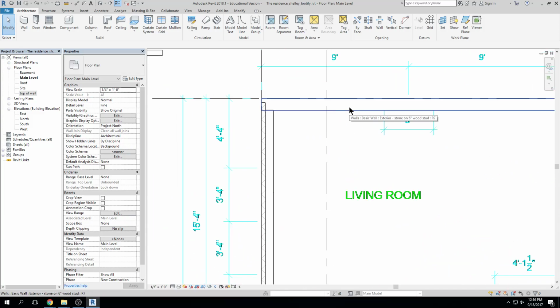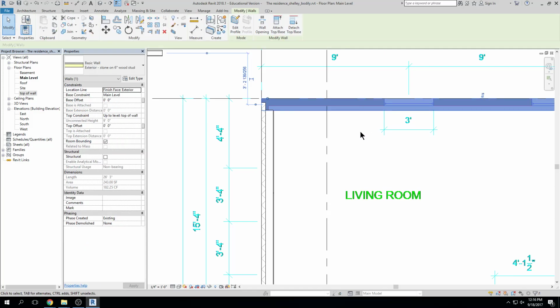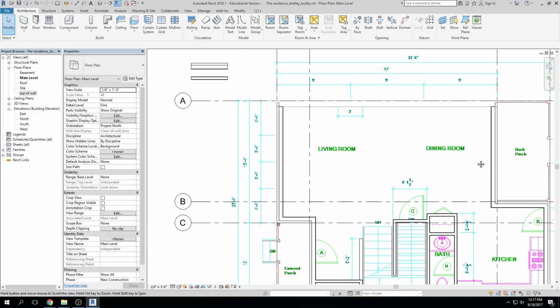Those of you that work doing construction can probably recognize this, right? Existing elements are generally either grayed out, or they don't have any definition to them. So they have a different visual appearance than brand new construction. Going back to the idea that plans need to be graphically correct and that you need to be able to look at them and read them like a book, existing items don't have as much definition and they're usually grayed out, okay? Items that are going to be demolished, taken out, are usually dashed, right? So we're going to start seeing some of those graphics happening.